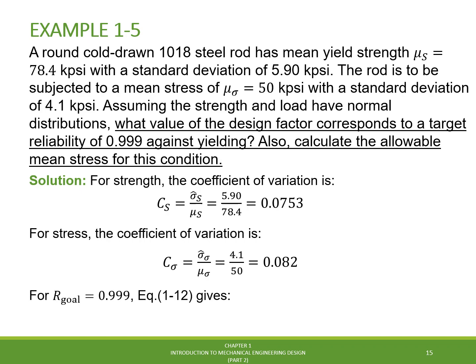Then the next parameter we need to calculate is the parameter z. Remember, the parameter z given by equation 112, we need to use the normal inverse cumulative distribution. Then we're going to apply that function as stated here in equation 112, and applying the parameter, which is given by our target reliability, we're going to get the result as 3.09.